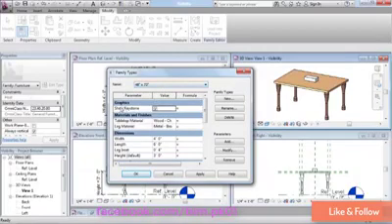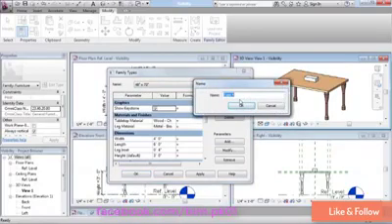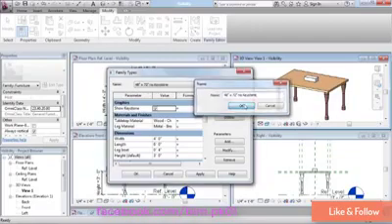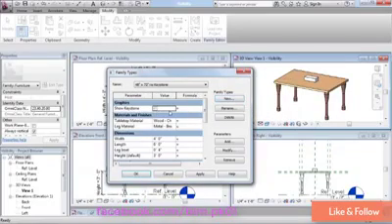Now you'll see under Graphics, here's our Show Keystone parameter. And for all of my existing types, it defaulted to On. So I'm going to switch to the type that I want to create, 48 by 72. Click New, and that basically copies the existing one. I'll call this 48 by 72 no keystone. And click OK, and then just simply uncheck the box.